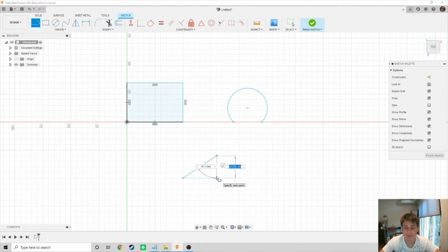And this occurs in other CAD software like SolidWorks and Inventor, because when you have a closed shape, you can do commands on it. You can extrude it to have a 3-dimensional solid shape. You can modify a shape so you can start working with fillets and chamfers, but you can't do that with an open shape because it doesn't have an area to extrude. You would want to use the open shape when working with construction lines, and we'll get into that later on.